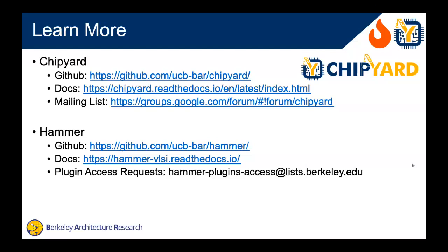There's a pretty wide range in setting up a technology plugin. It's very easy to get GDS out. For a Hammer developer or someone familiar with the tools, it's pretty easy to go from nothing in a file to a plugin that will get you GDS out. And then the hard part becomes cleaning everything up and making sure your designs come out DRC and LVS clean the first time with your tech plugin. That involves more iteration. There are certain standard cells that have problems.